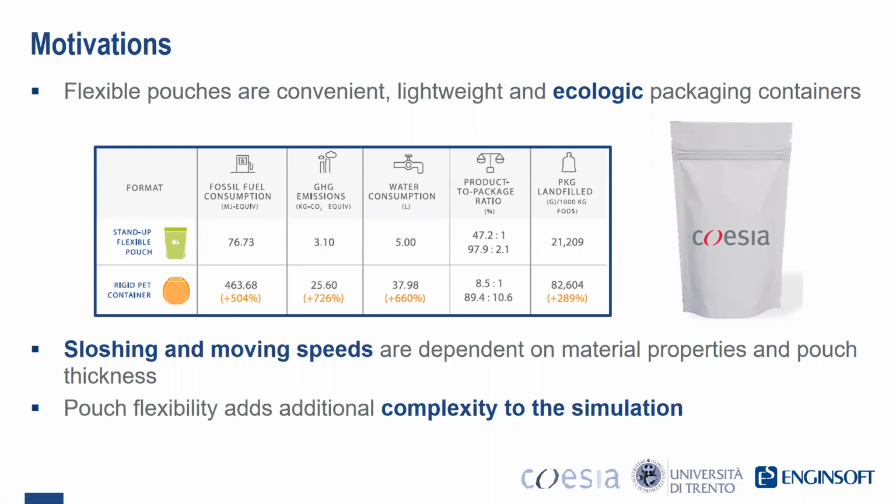And of course, the flexibility of the pouch increases the complexity of simulating this kind of system, because we will see also examples of, let's say, types of PET containers, like bottles, that are not so flexible or deformable. And this type of simulation was already performed with the coupling between Particleworks and RecurDyn, but the novelty of the approach here is that the pouch is very flexible, and only RecurDyn can study that type of material.